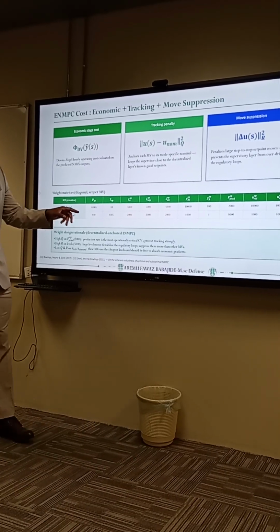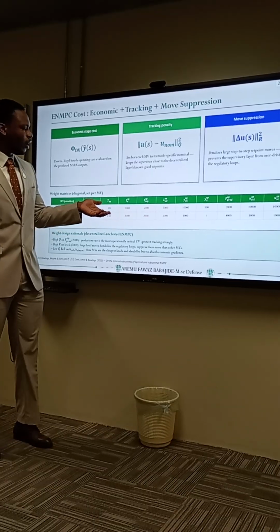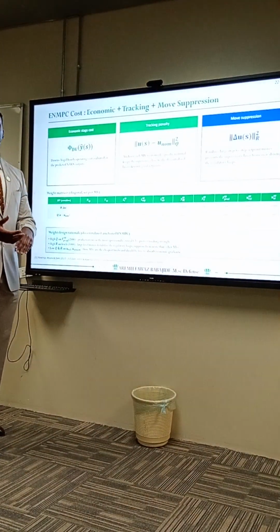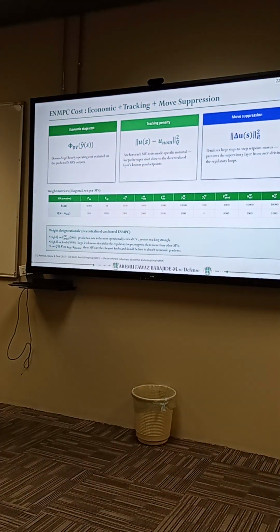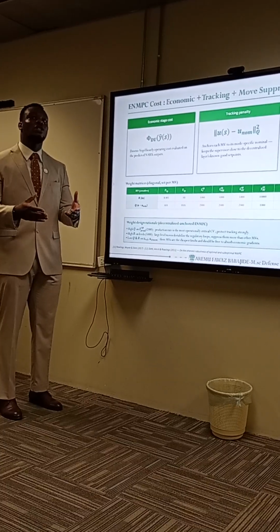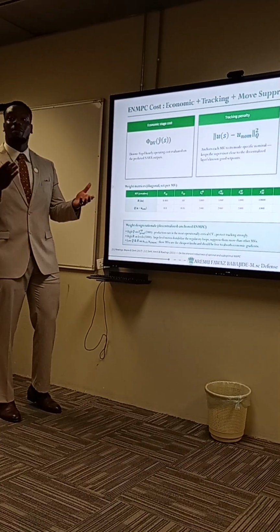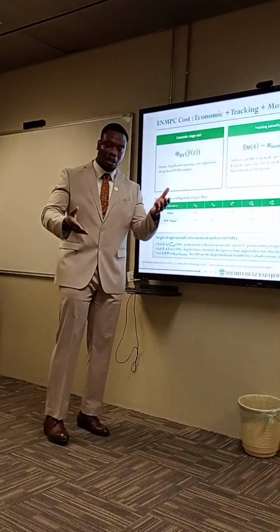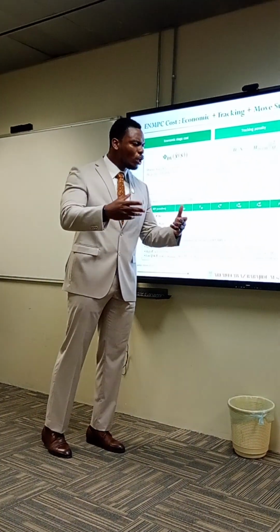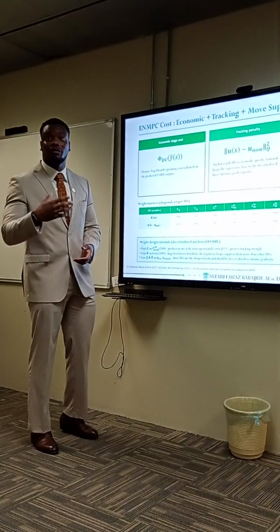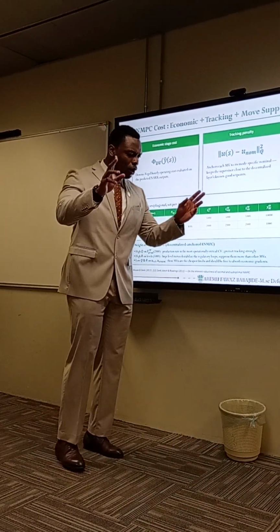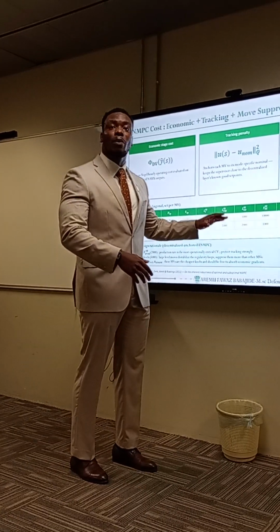Now, if you pay attention here, you see we have a lot of weight penalty on the levels, because in plantwide control, and when you check a lot of plantwide control papers, you have to be able to stabilize the inventories. The inventories are basically your levels, your tanks. If you have perturbation, if you have your tanks not stable, moving up and down, you're not going to have a good consistency when it comes to the feed composition. Basically, you have oscillating composition.